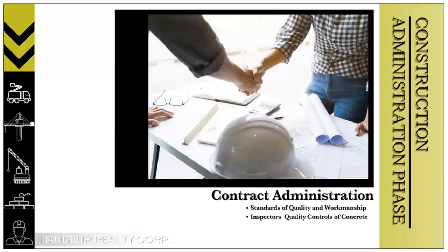So, we need to have a laboratory to test the structural concrete. The concrete used on the site must be verified for strength and other properties by independent concrete testing laboratories. What we mean by strength there is, for example, 3000 psi, 2500 psi, 3000 psi, and each has a corresponding curing time like 7 days, 14 days, and 28 days.